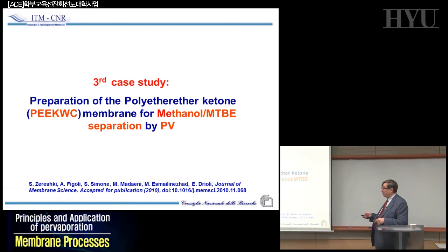And it's interesting because the polyether-ether ketone is not soluble in any solvent, so you cannot use NIPS, TIPS, or the traditional phase inversion. But if you make this chemical transformation, you introduce this cardo group, this lactone group. This lactone group gives a lot of solubility in traditional solvents. And so this material becomes easy to cast into porous, dense, or asymmetric membranes, depending on what you want to do. This is the case in which we have been using this polyether-ether ketone for the methanol MTBE separation. That years ago was very interesting.